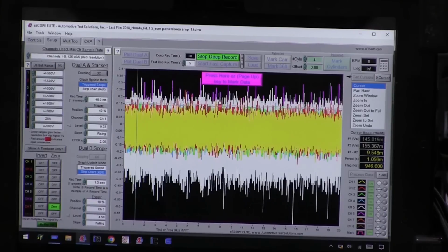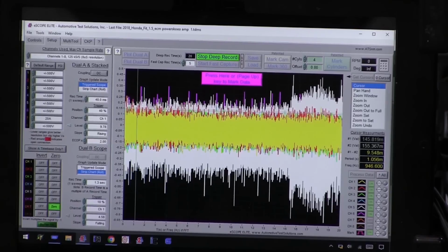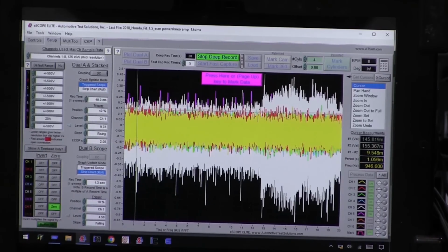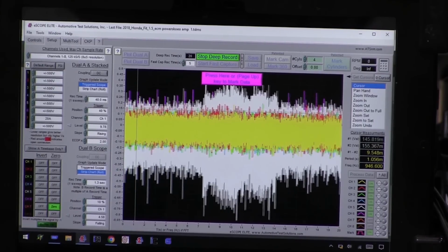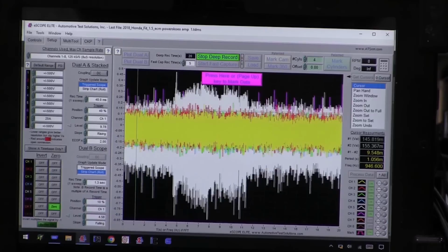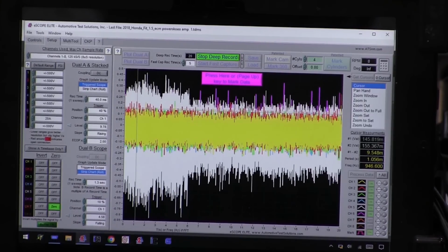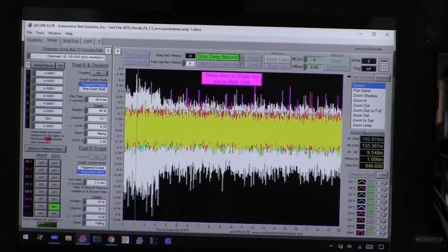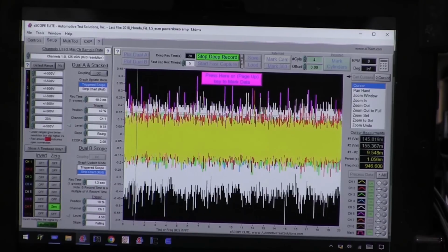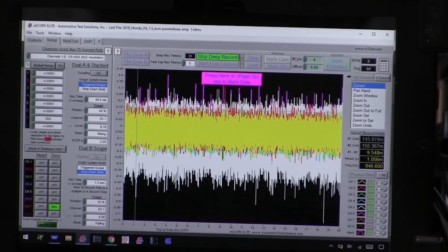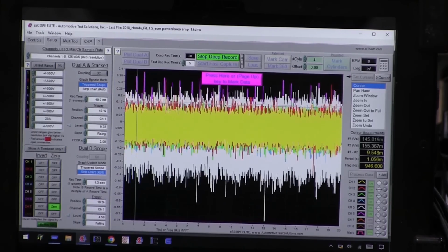Once again, I'm going to unplug it. And we can see it gets a little bit bigger. And I'm going to plug it in. But I've checked lots of throttle circuits on vehicles, and they always have noise from that motor control system. The H bridge always puts noise out on the circuits around it. And the ground we're in must be the ground for that throttle control. We can see that right away just because the frequency is so fast. There's not a whole lot of things on these motors that work with that kind of frequency other than a throttle control.